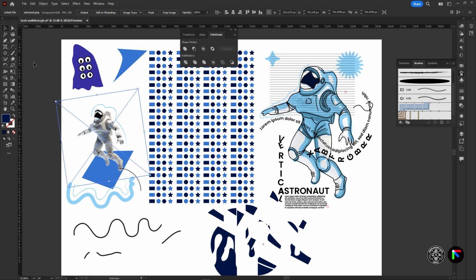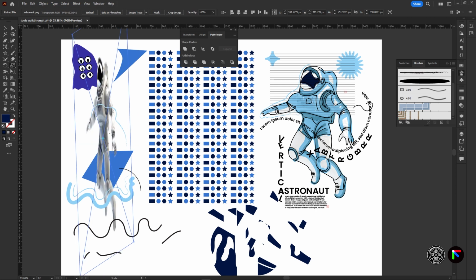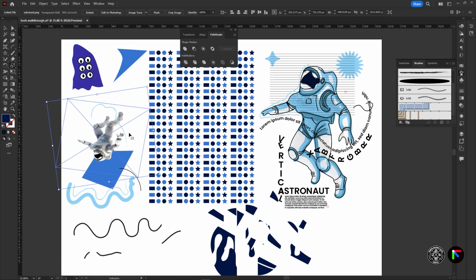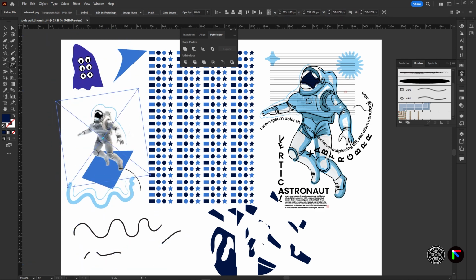And then we also have the scale tool. The scale tool helps to resize objects around a fixed point. So if I pick my scale tool, I can actually scale my object like this, or like that, or anywhere I want it. I can also use shift to hold your objects in place. But most times, if you want to scale your object, what I do is just use my selection tool, holding my shift and alt, and clicking and dragging to scale my object up, like so.